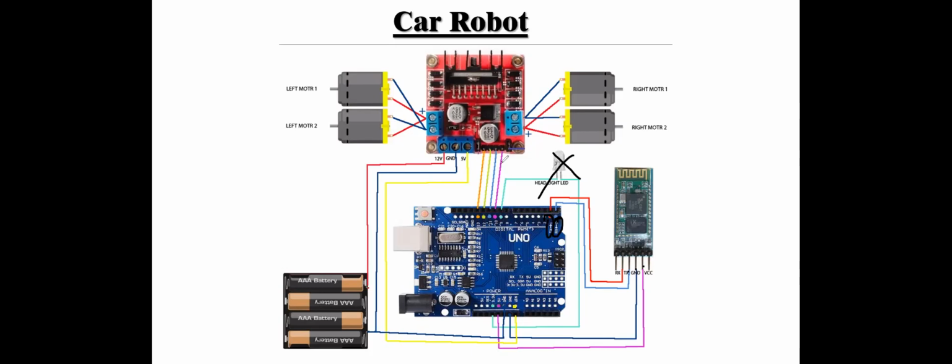Right? So they have wired up the pins 10th, 9th, 8th, in1, in2, in3 pins are wired. You can see here that these are jumpered or short circuited. If this is not short circuited, what you have to do is obtain a female to female cable, right? Then you can simply connect these two terminals, and connect these two terminals. Now we have in1, in2, in3, in4 pins that are connected to the Arduino. Right? This is very simple.